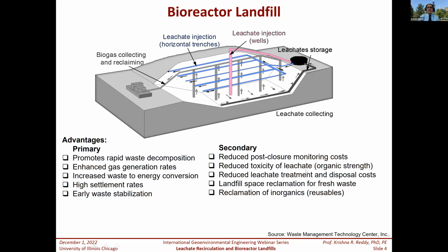As a result of that, a lot of wastewater treatment plants don't want to accept the leachate, even if you want to pay them for the treatment, because their systems are not designed for such high organic strength liquids. So you will have a lot of issues with getting rid of high organic strength leachate. But here, you are simply doing the leachate recirculation. That organic strength might even benefit enhanced degradation.